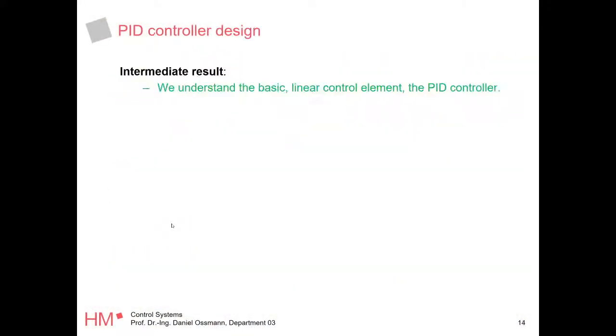For me, at this stage, it's important that you know a PID controller is an ideal view of a PID controller, because for implementation, you additionally need to add this parasitic delay. Otherwise, especially if you do a project or something and design a controller, and then you need to code it in C or on your Arduino chip, you will run into troubles when you don't consider that, because it simply will not work. Okay, so this was actually all at this point for the PID controller.